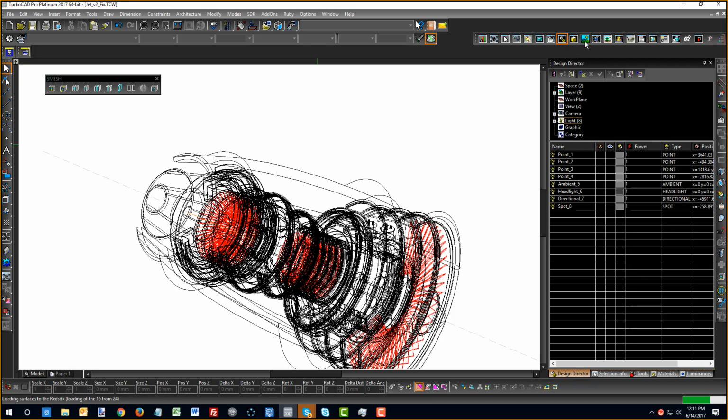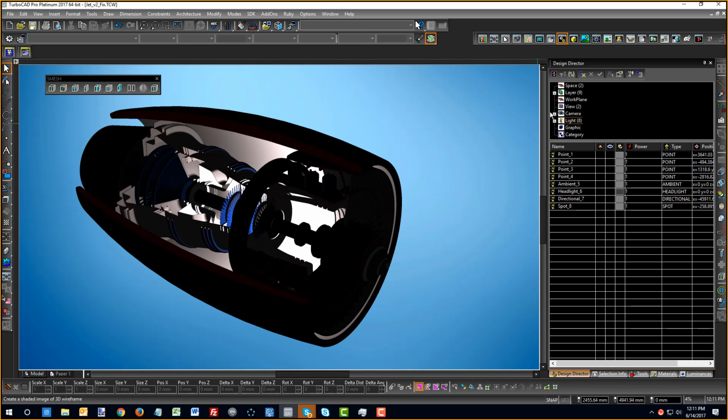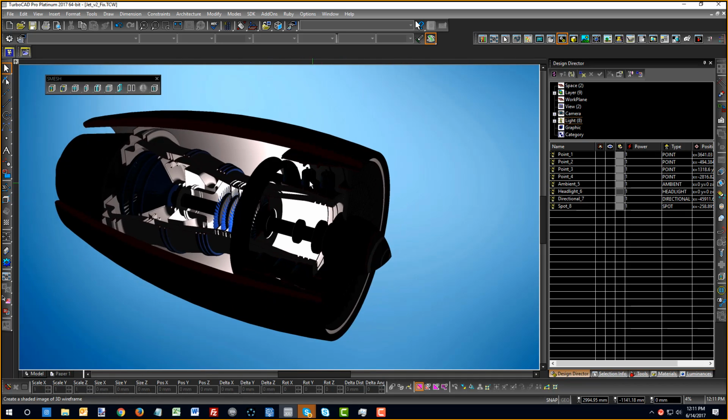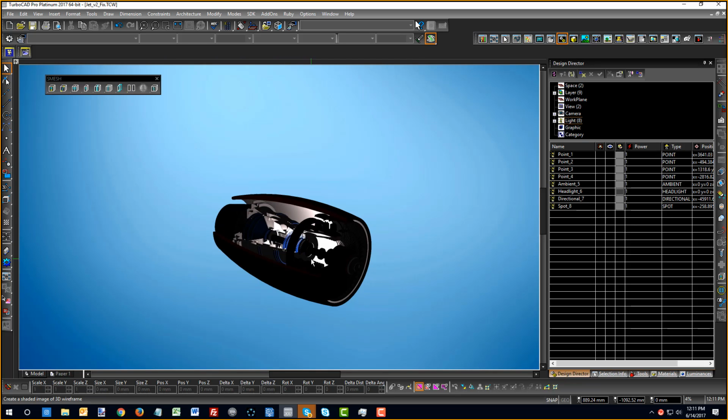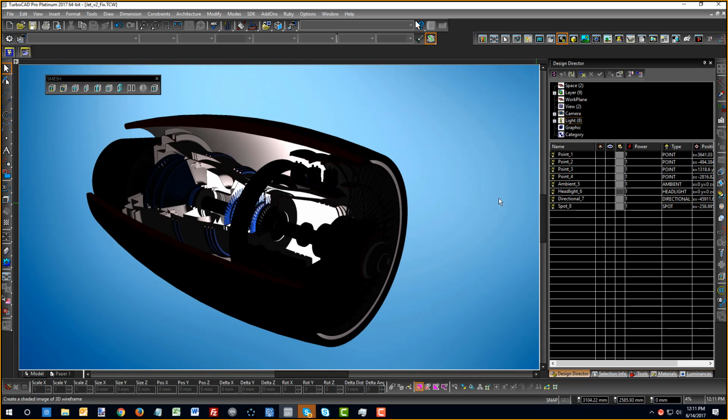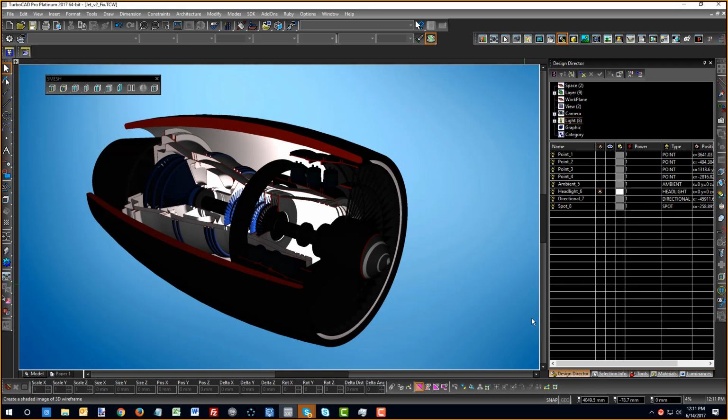The other thing to point out is that you're actually seeing the Luminance objects in here. I thought they were spheres, but maybe he used a different type of object. Because I'm using Red SDK and only Luminance objects, I don't have any of these ambients on, so the draft mode will look a little bit weird. I think we can turn the headlight on to work in draft mode. That's normally what I tend to do. And if I bump this up, I'll get a little more light here. The headlight is directly in there. So he's got his Luminance objects in there.